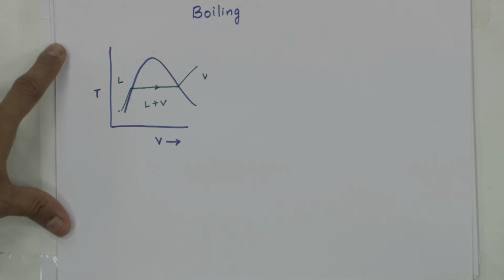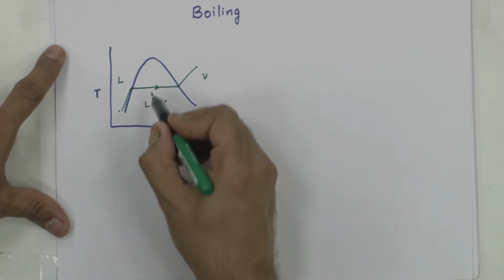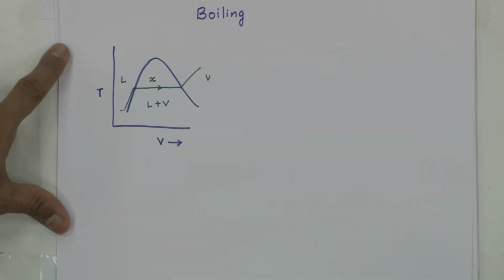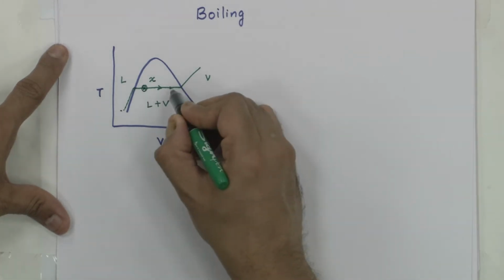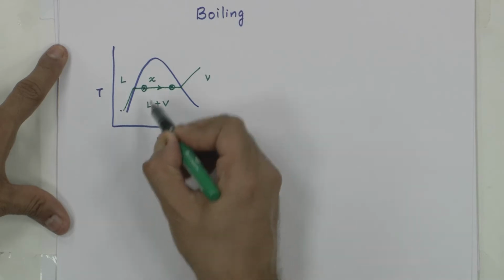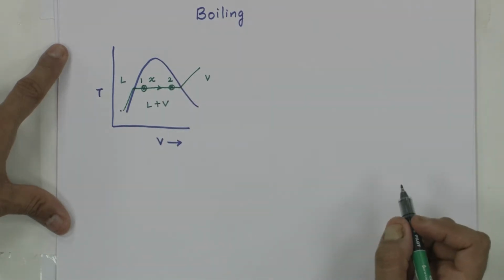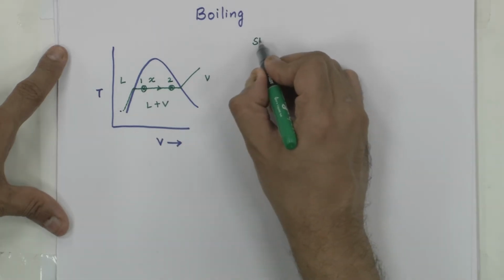This we have seen in basic thermodynamics, and in this region you needed an additional quantity called thermodynamic quality, given by the symbol X, which was necessary to identify whether I was in this location or this location. This would be a low quality situation, 0.1 here, 0.2 would be a higher quality situation, and both of these cases, state 1 and state 2.